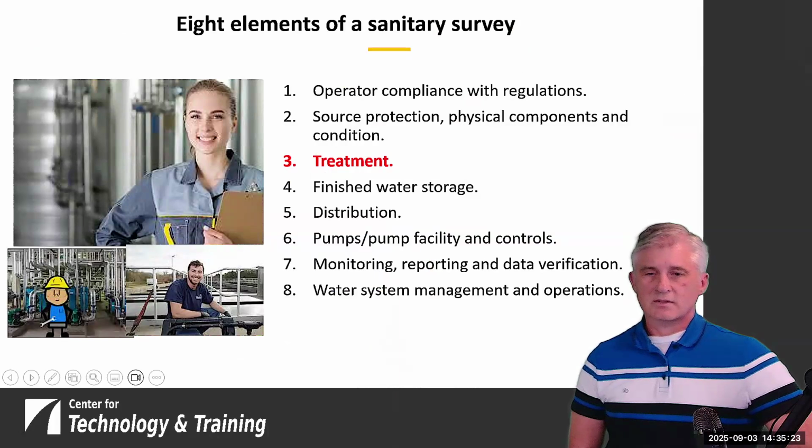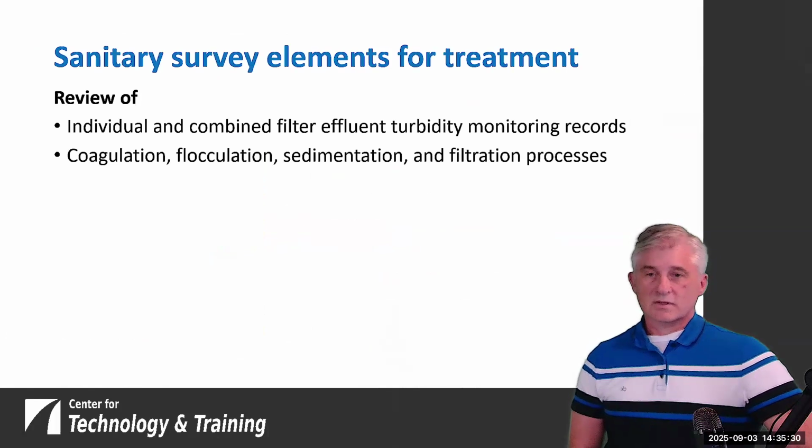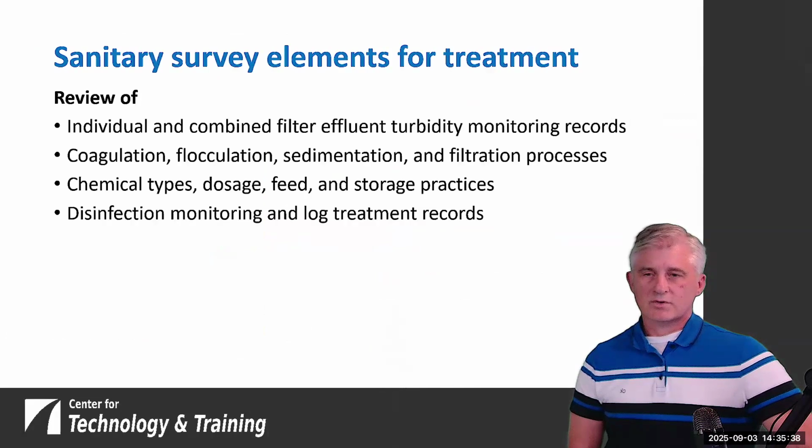There are several different things that the regulating agency will look at. They're going to review those individual and combined filter effluent turbidity monitoring records. They're going to look at the different processes that you have in your treatment plant.